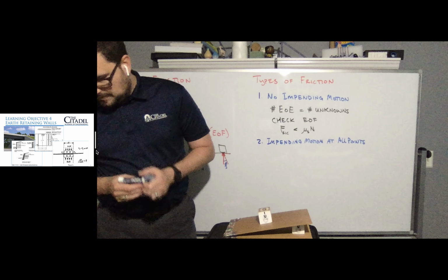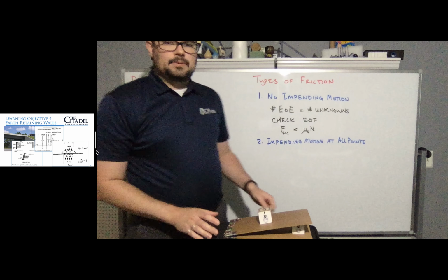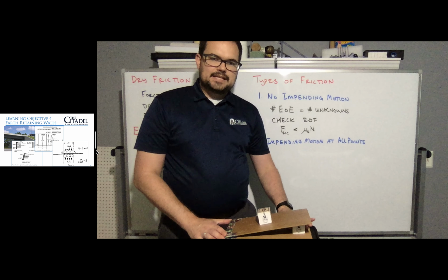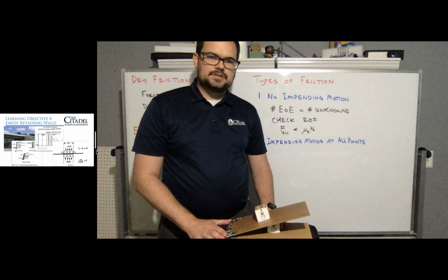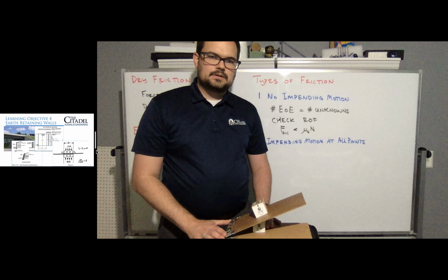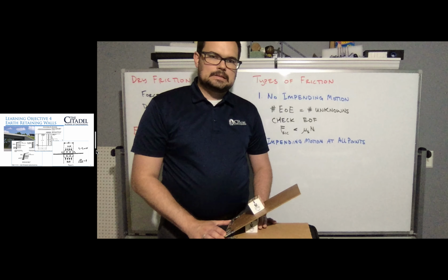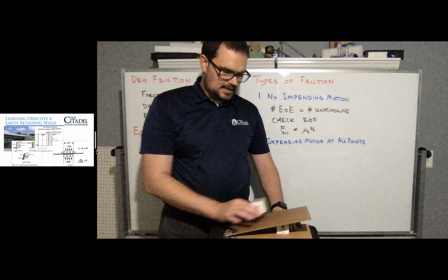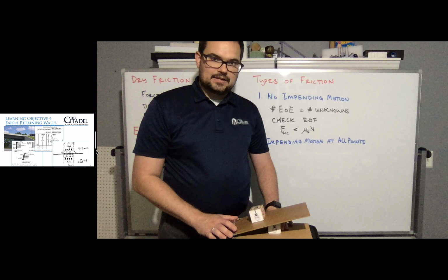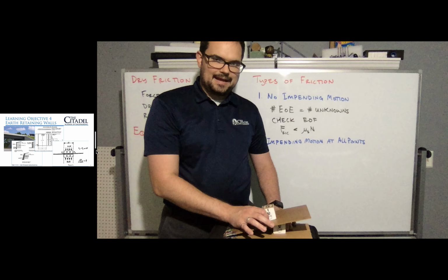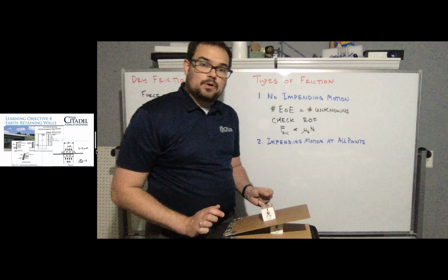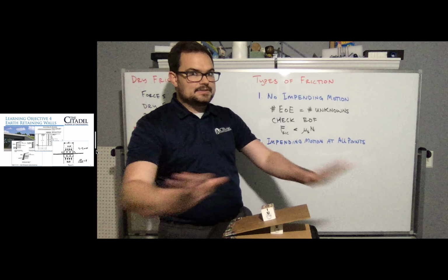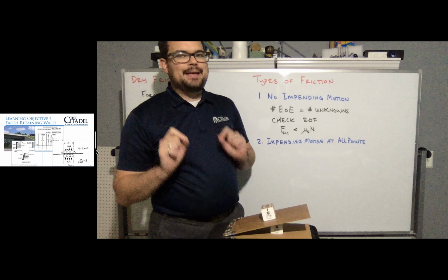An example of that would be something like, if we look at my little block here, I can actually increase the angle of the ramp until that block on top starts to move. See it start to move? Something's going on, it's acting a little stuck, until it starts to slide. You'll see how it's sliding now? Okay, so I'm going to back it off just a little bit, and I'm going to get it right to where it's about to slide. So if I do any more increase, it'll start to move. But remember, this is statics, nothing moves. And so we're right at impending motion.